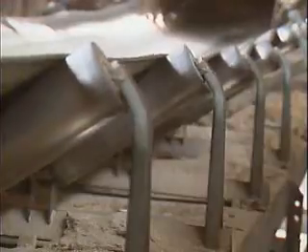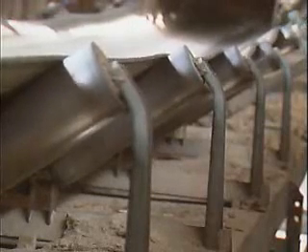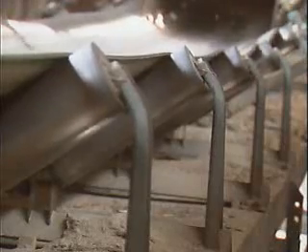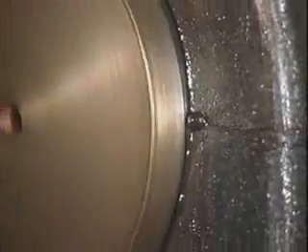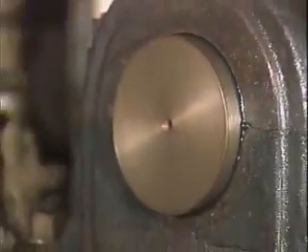There are various reasons for using grease, most of which depend on the operating conditions in a given situation. Under certain conditions, grease may be necessary to ensure that the lubricant will stay in place. As long as grease remains semi-solid, it tends to stay where it's put. Oil is much more likely to flow away from where it's needed than grease is. Even when both oil and grease would flow out of an area, it's much easier to retain grease with a seal than it is to retain oil.